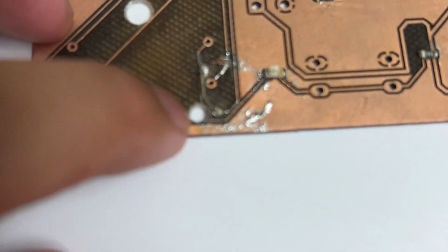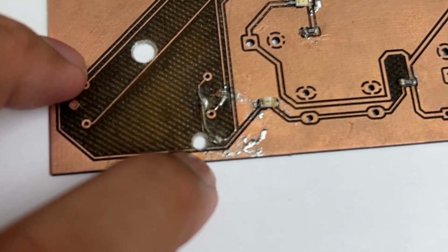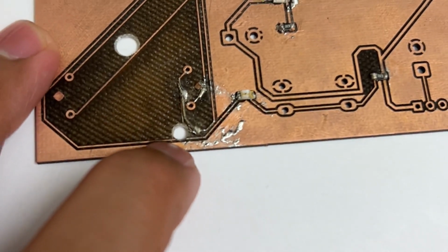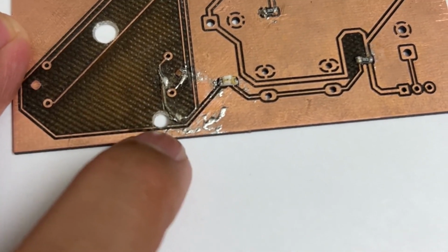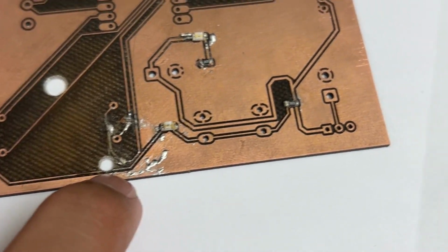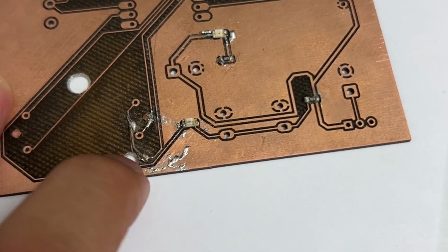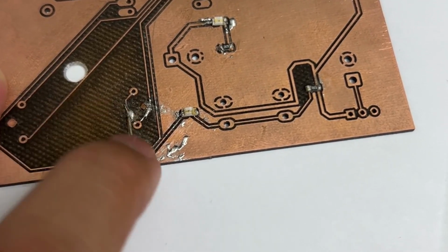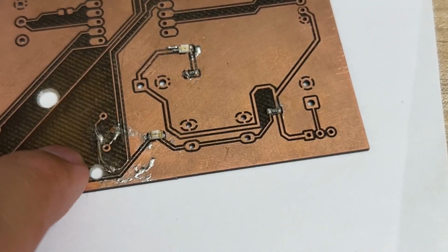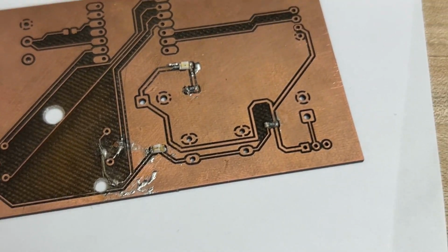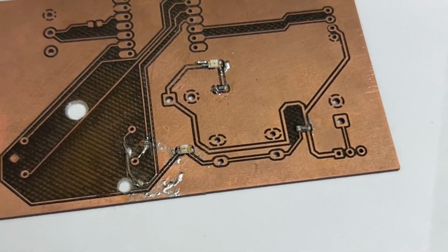And yes, there's another thing for this board, which is, as you can see here, there's a drill hole on the board, but this should be one track, and it is being separated by this drill hole, totally cut off, and this wire is broken. So it will be super difficult for you to fix it. I tried to fix the upper track by using a wire soldered on both sides, and I had to use tape to glue it on the board, and then use the tweezers and soldering iron to solder both sides on the track. It will be super difficult, so do avoid that.